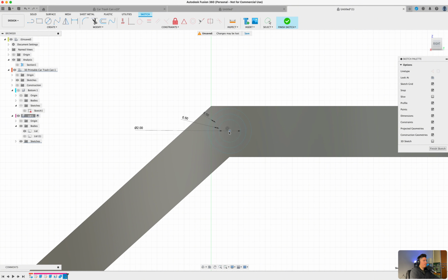Now we're not really relying on anything specifically, but if we wanted to, we could set some dimensions for this. So select that circle there, maybe 2.1, 2.2. All I did was set a dimension, selecting this top circle and this line here, and now we set up some constraints. So now we can't free move it, we can only move it left and right.